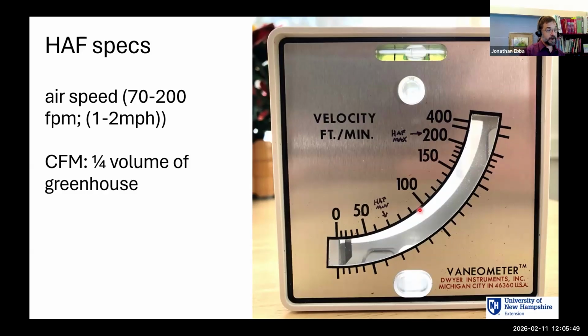When we're planning this for our house, we want to do 1/4 of the volume of the greenhouse. So we're saying volumes, that's cubic feet. We can imagine like a foot cube, right? And that much air, all that air in the house up to a level of 8 feet. We want to take 1/4 of that, and we should be able to move that per minute. And this is cubic feet per minute. And when you buy a fan, it should tell you how many cubic feet per minute that fan moves, right?